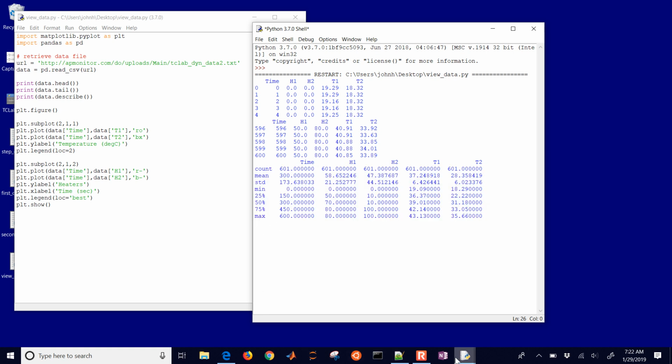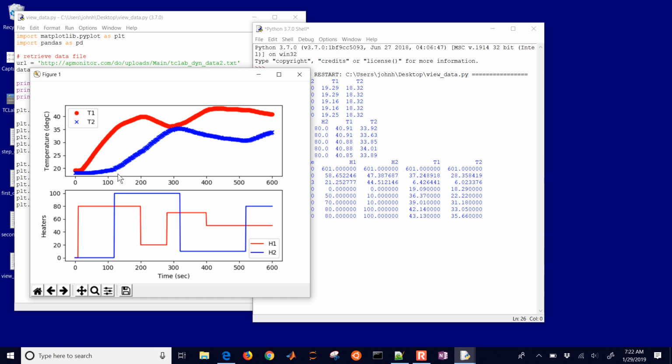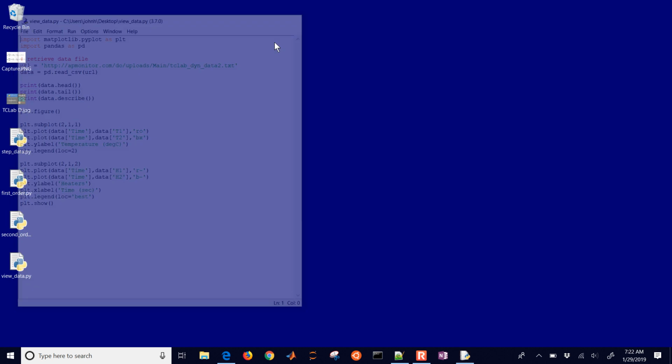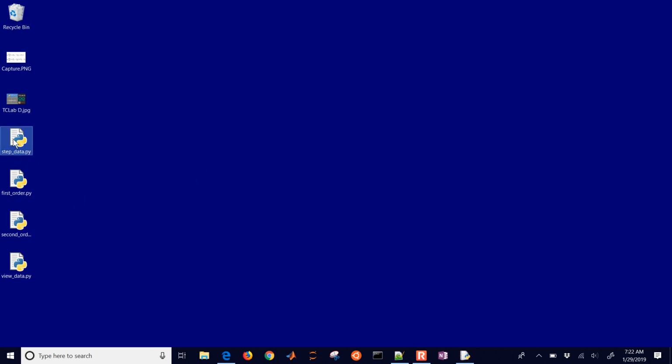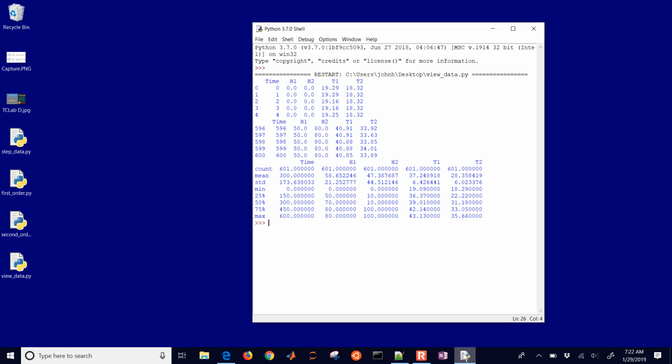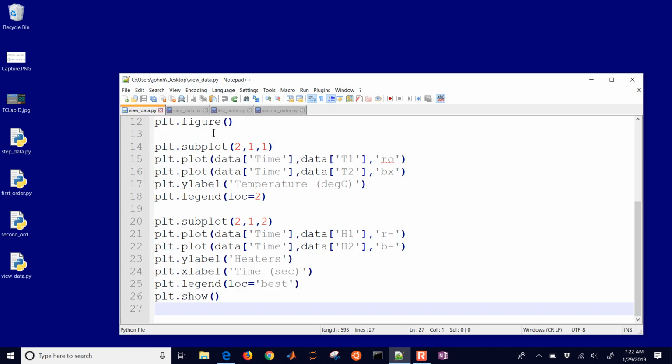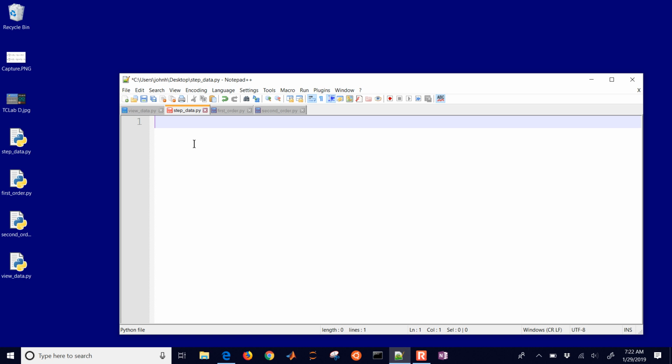The important thing here is just going to the data. You look for any outliers or anything that might cause a problem for your identification. So I think we're ready at this point. I'm also going to start the collection of step data. Go ahead and get my own data. If you have your own temperature control lab device, I would recommend just generating your own data.